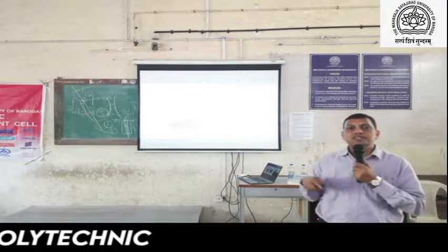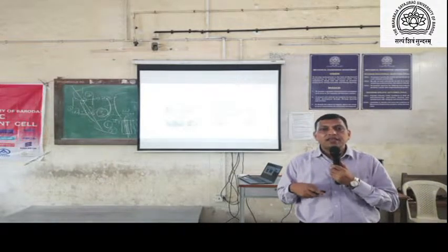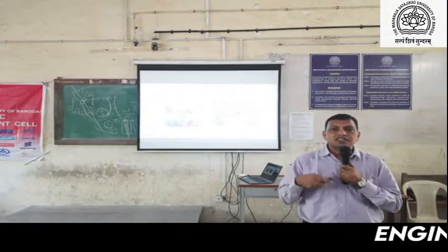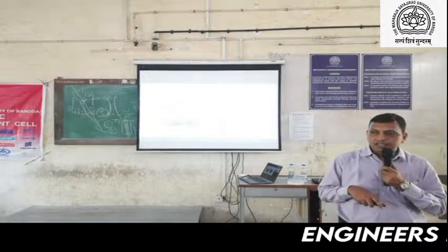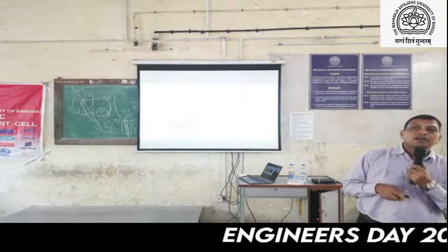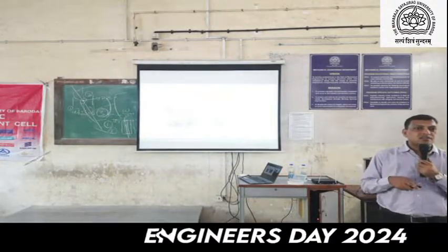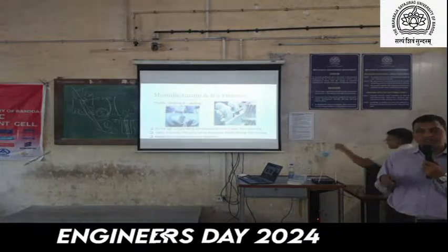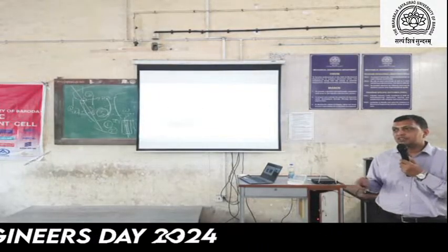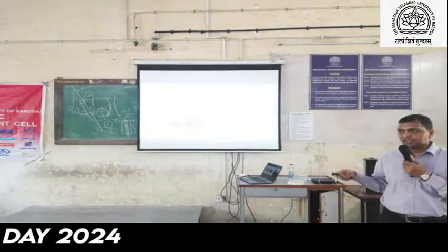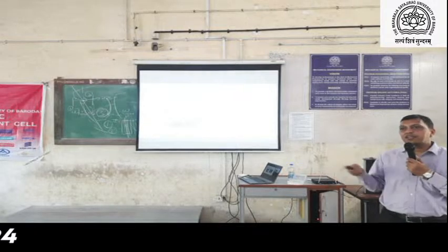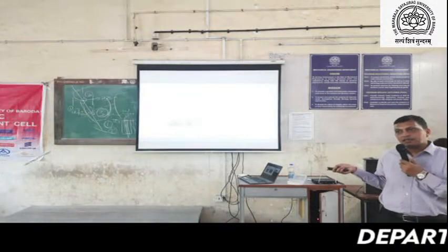When the surface roughness is high, it cannot be called a highly accurate gear, and that will impact our operation. Grinding can smoothen the operations, reduce the vibrations, and give good contact. So all these parameters we can maintain in the grinding operation.